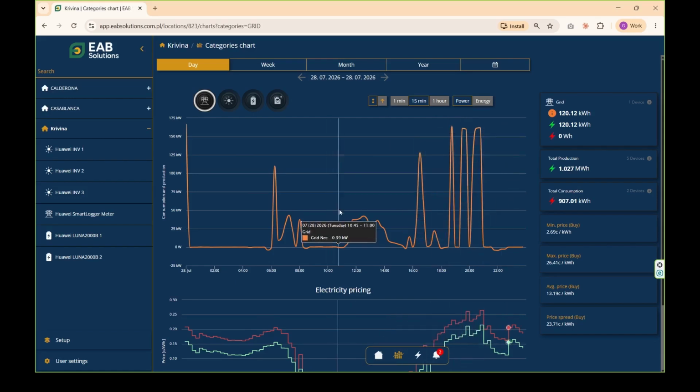The client will ask, why haven't we stored this energy here in the battery? Because the battery, in the end, is sized for a case, for maximum return for the client. But maximum return for the client per kilowatt hour of battery isn't always an infinite battery. So there will be moments when there are PV surpluses that don't fit in the battery and have to be sold at whatever price if the client doesn't consume them in their own factory. The beauty is in how we size it.